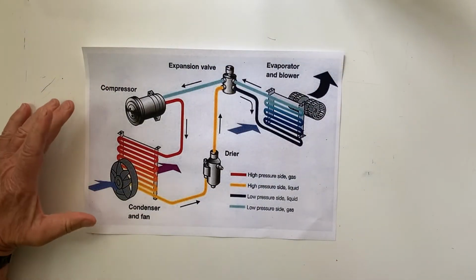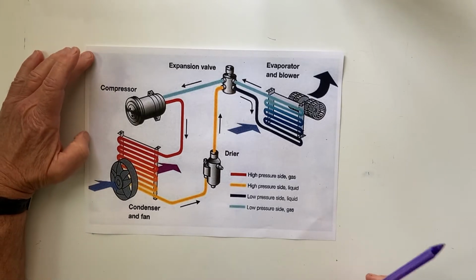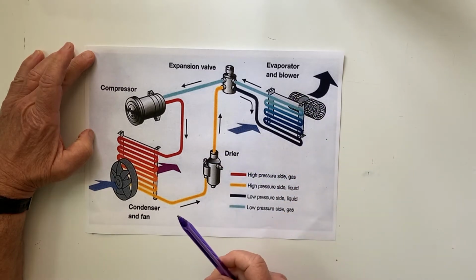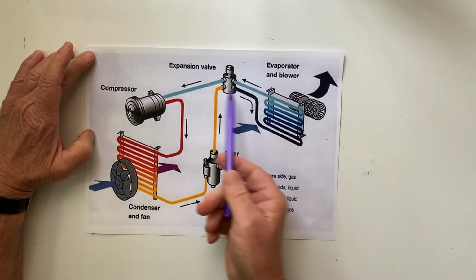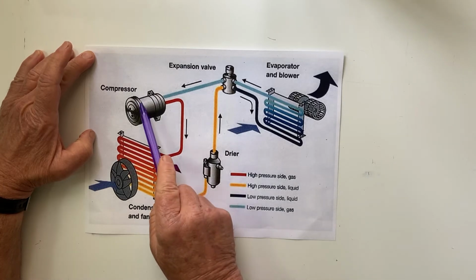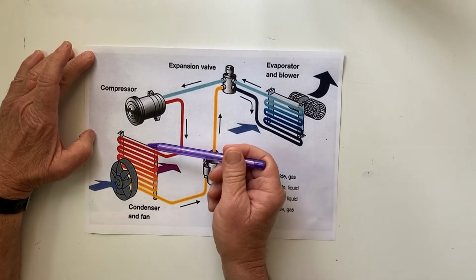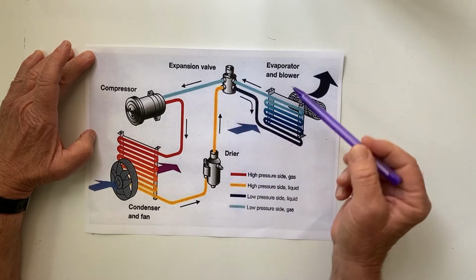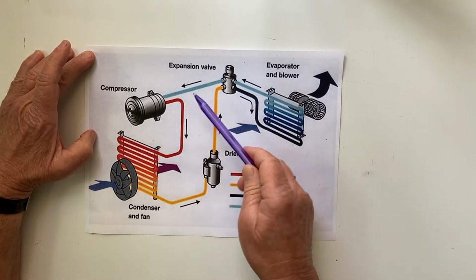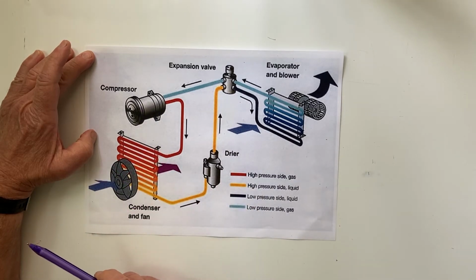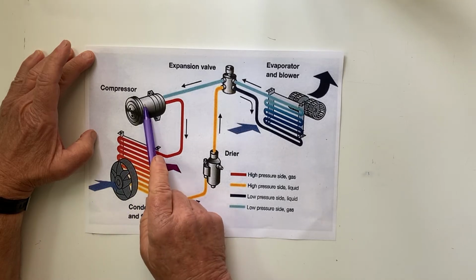Okay, so now we've been through the basic concept as to how the air conditioning system works. We're going to look at a system and make sure we understand every one of the stages as it passes through each cycle that the air conditioning refrigerant takes as it moves through the system. The different components that we've got are the compressor, the condenser, the receiver dryer, the thermal expansion valve, and also the evaporator. Now each one of these components has its own particular task. The one that is driven by the engine is the compressor, so that's where we'll start.